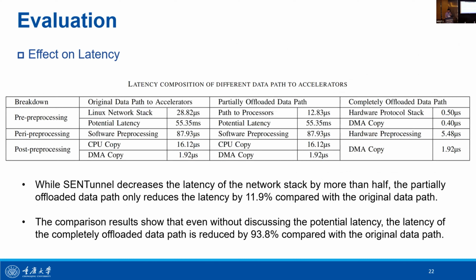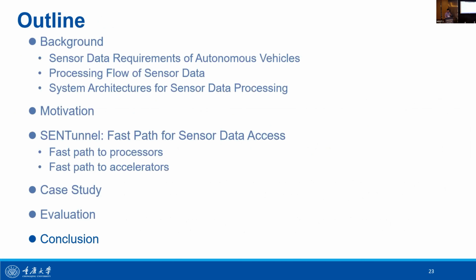Finally, we compared the latency of an MSOP packet from entering the embedded system to reaching the accelerator. The comparison results show that the latency of the completely offloaded data path is reduced by 93% compared with the original data path. Next is the conclusion of this work.